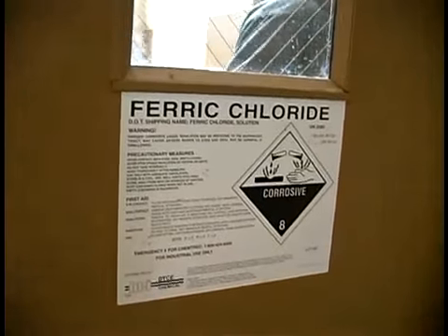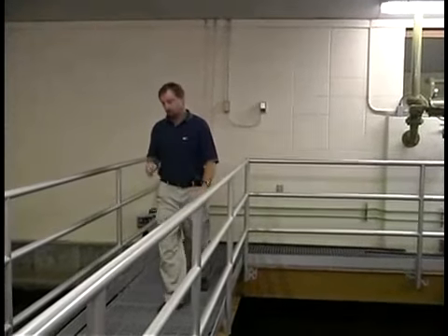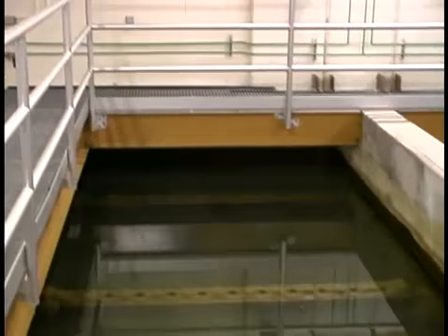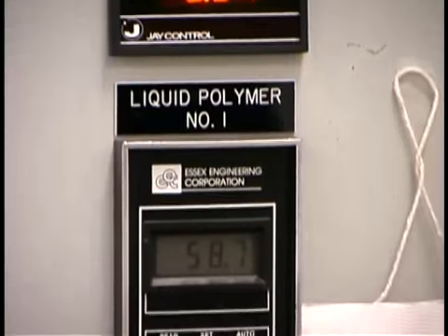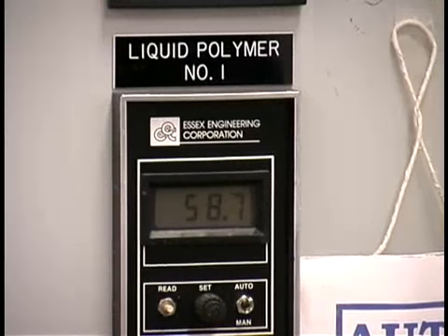Our approach here is to also use ferric chloride. When we get above 8 micrograms per liter in our finished water, we start adding ferric chloride. This is also being considered for Lockwood. Right now, like I say, we are testing a polyaluminum hydroxide. We're not sure if that's the polymer of choice or the coagulant of choice. Right now, we want to be able to feed a little bit of ferric to get rid of the arsenic, but we want to get that into some level that's more controllable for pH. But I would imagine that that's probably where we'll be 6 months from now.